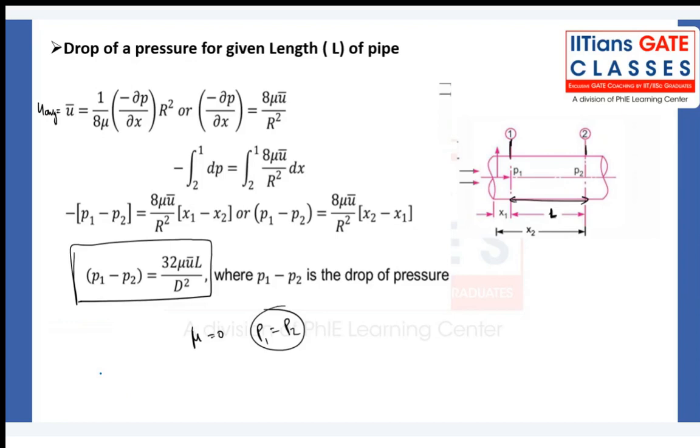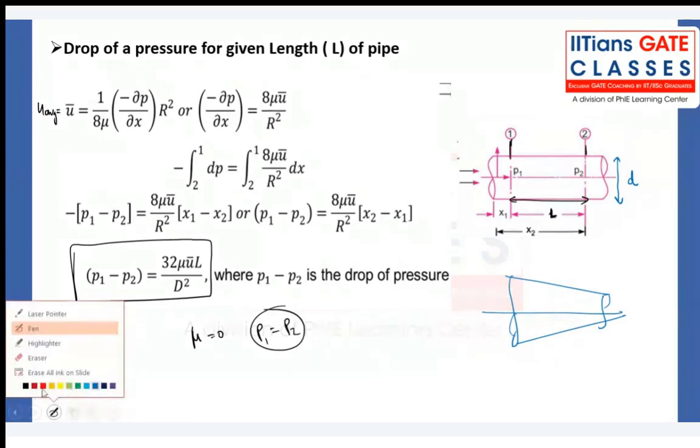Total energy will remain constant or not? Already the diameter of the pipe is fixed. Velocity cannot change, average velocity cannot change, right? Unless you have a segment like this. I'm not talking about this extreme case. I'm talking about a simple flow through a constant diameter pipe, with a fixed diameter. And when it is a horizontal pipe, there will not be any potential difference also. So I'll be getting this formula. Quickly note down, then we can discuss some problems regarding this.